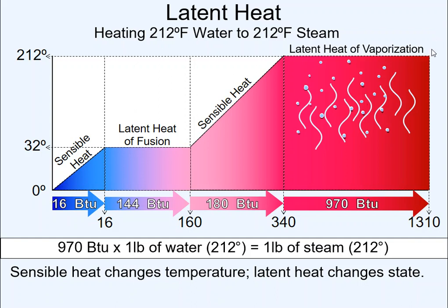So if you can imagine another line over here to the right, this one doesn't have that drawn up. But once you get to 100% steam, you could keep heating that up. You could pressurize that, and you could what we call superheat that steam. Power plants do that a lot. So once they bring that back down to the point that it hits its saturation point, it's going to go through a process called what? Condensation, right? Condensing.